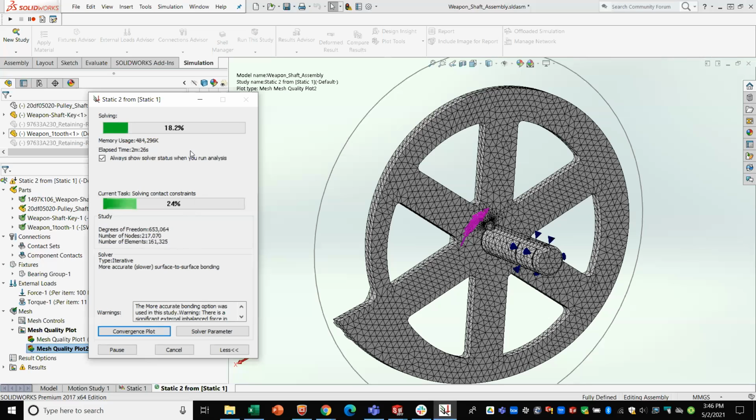If you try and simulate a problem and it runs for an hour and then fails, that's something that's really going to annoy you as a designer. And if you keep butting your head against the wall trying to keep that really high mesh density, no penetration contact in there, it's going to keep happening.